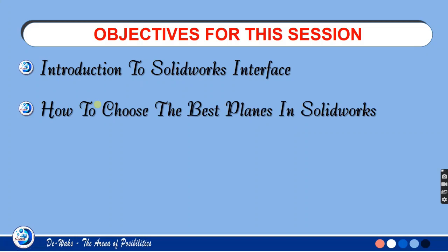In our earlier tutorial, we learned more on introduction to Solidworks interface, and then we started learning how to choose the best planes for your drawings and models in Solidworks. We only learned in that video how to use the front plane. In this one, as we continue to look at introduction to Solidworks, we are also coming to learn about how to use the top and the right planes and when and where to select them when doing your drawings and models.